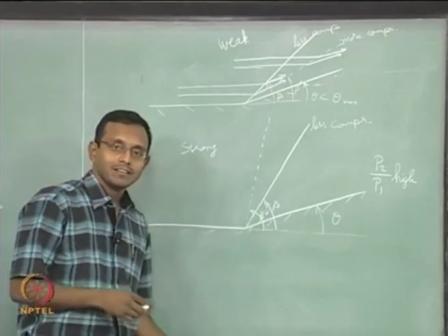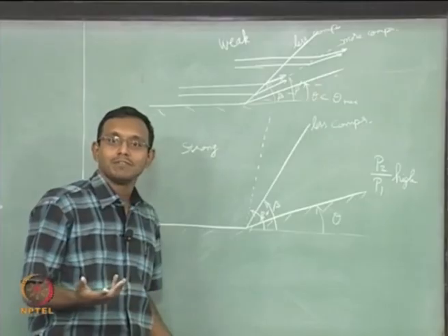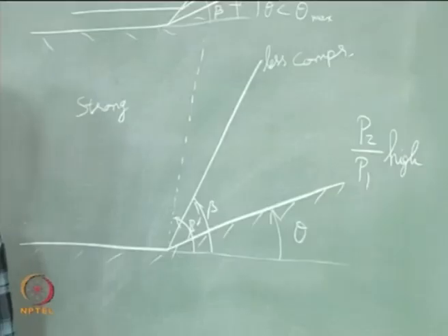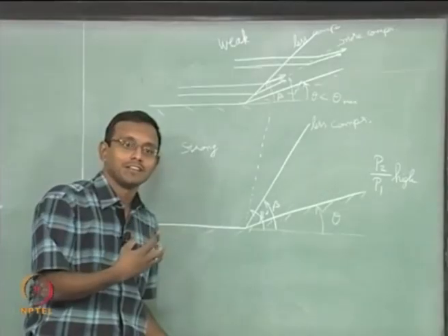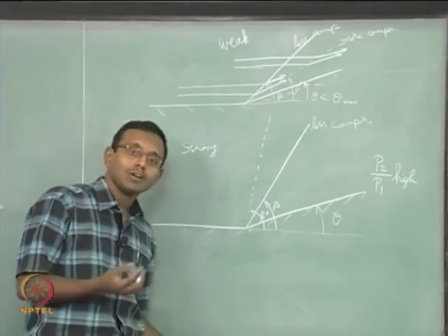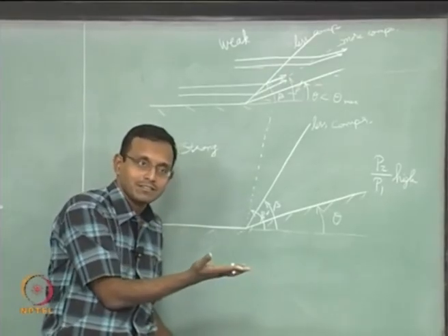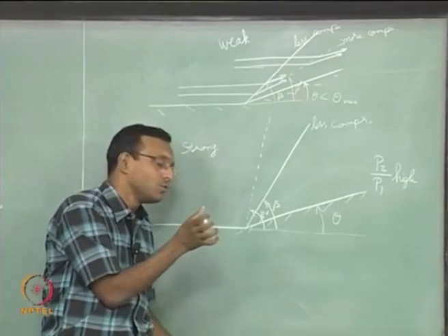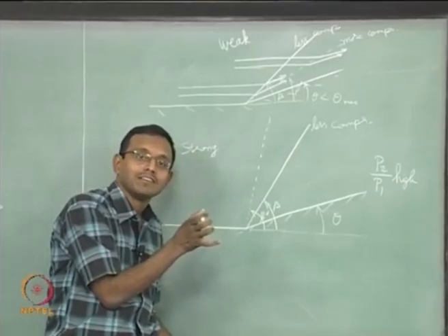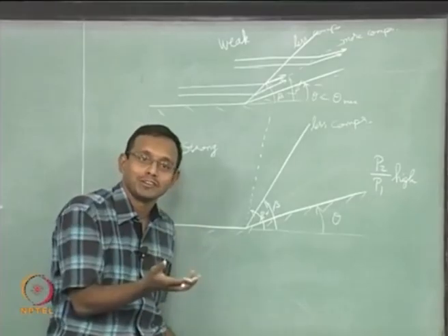To make it very high, that is I have to form pressure energy a lot. Where is the energy coming from? It should be from the fluid. So, it is coming from the bulk kinetic energy, the kinetic energy of the fluid element. Okay. So, there should be a lot more kinetic energy to be processed. If I decrease my beta, my U1 normal decreases, which means I will not have enough kinetic energy incoming across the shock.